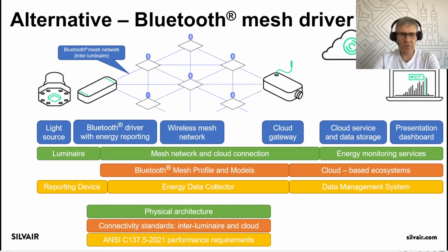So you may be looking on the market for integrated Bluetooth drivers. And this is a growing category. Of course, at this point, because DALI has been around for many years, there is a broader selection of DALI drivers than integrated Bluetooth drivers. But of course, if you find an integrated Bluetooth driver, it may very well serve the purpose, and it even simplifies the system because the driver does the energy monitoring and reporting by itself. It doesn't need any other connection.